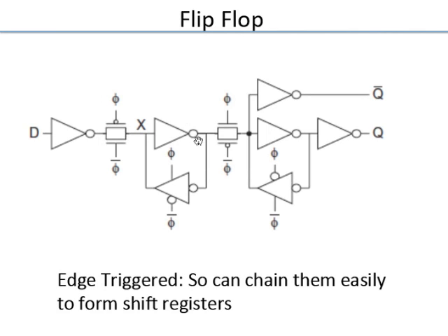And the flip-flop is just putting these two latches together. A flip-flop is edge triggered, whereas a latch is not edge triggered. It's a level sensitive design. When the transmission gate is on, D comes, Q follows D. Only when you close the transmission gate does the latch hold the information.